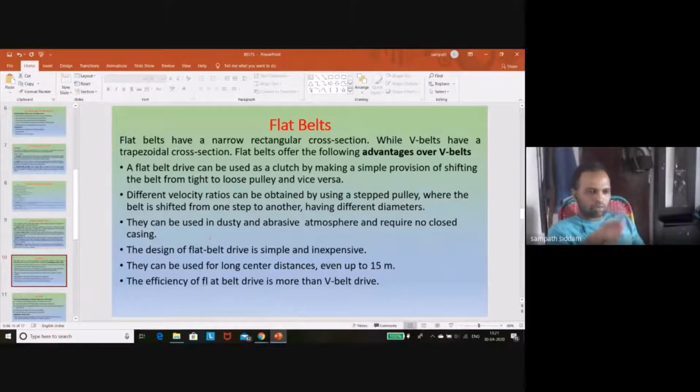For this cooling system you have a radiator. The water present in the radiator collects the heat from your automobile and allows it to move on to the atmosphere. In order to have faster cooling, you have a fan placed over there. This fan is usually driven by a belt, that may be a V belt or a flat belt.